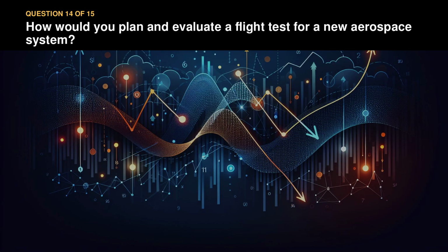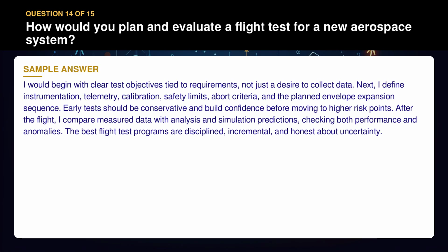How would you plan and evaluate a flight test for a new aerospace system? I would begin with clear test objectives tied to requirements, not just a desire to collect data. Next, I define instrumentation, telemetry, calibration, safety limits, abort criteria, and the planned envelope expansion sequence. Early tests should be conservative and build confidence before moving to higher risk points.